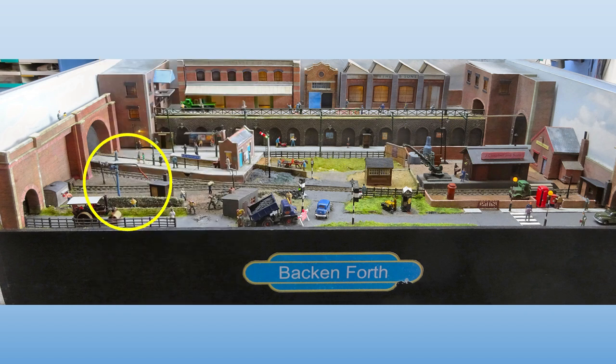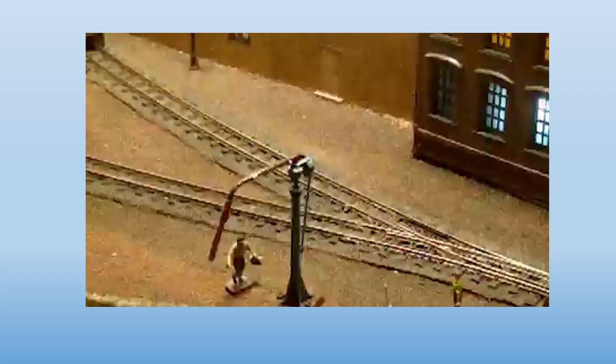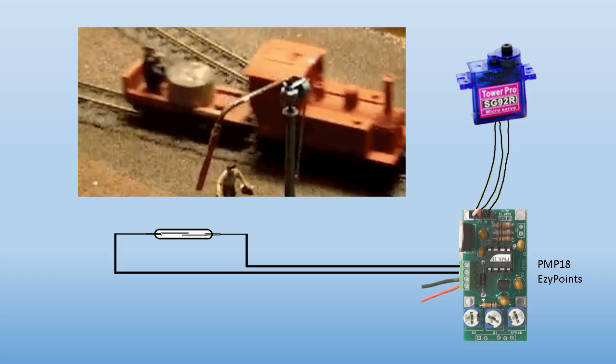On the left of the layout is a water crane that comes round when a loco enters that particular siding. Again, a simple operation. There's a reed switch under the track and the load in the wagon is in fact a magnet. When the loco comes into the siding, the magnet operates the reed switch and the switch triggers the Easy Points kit to swing round the crane, as we can see here.